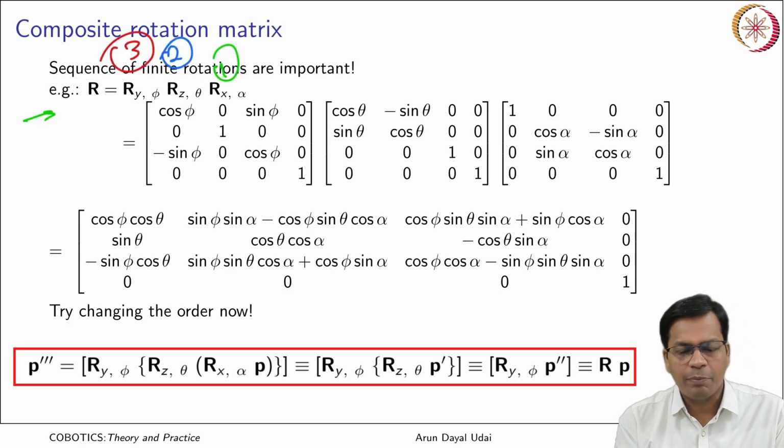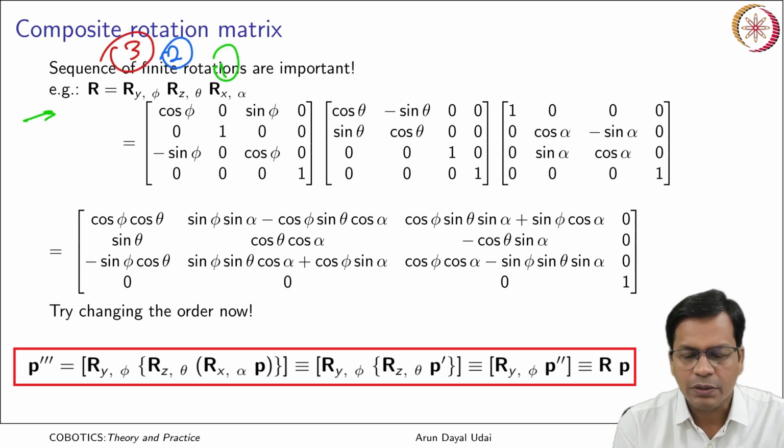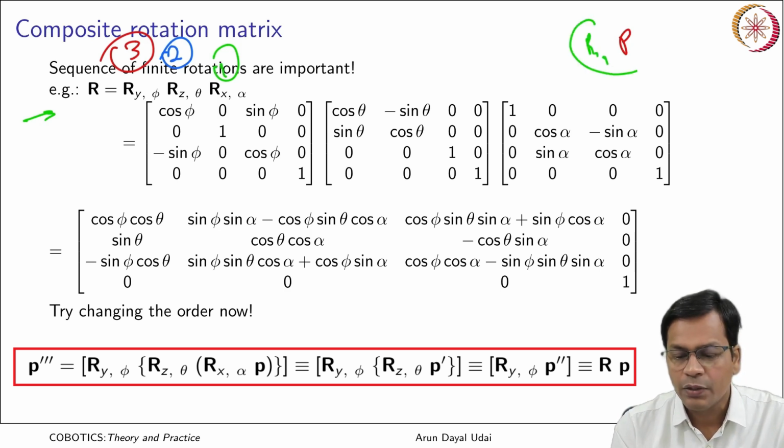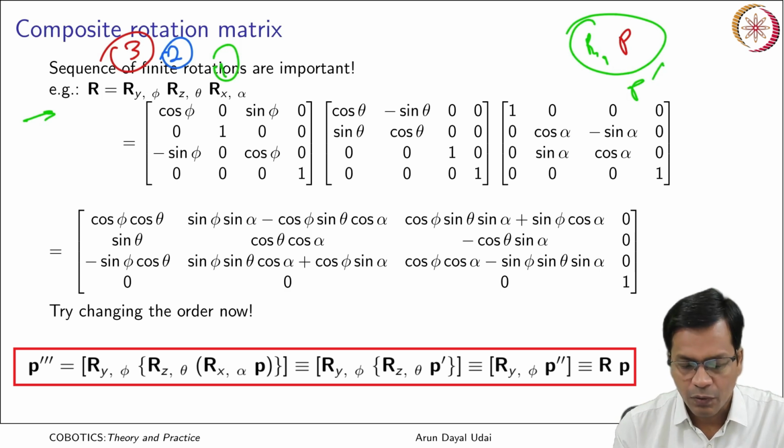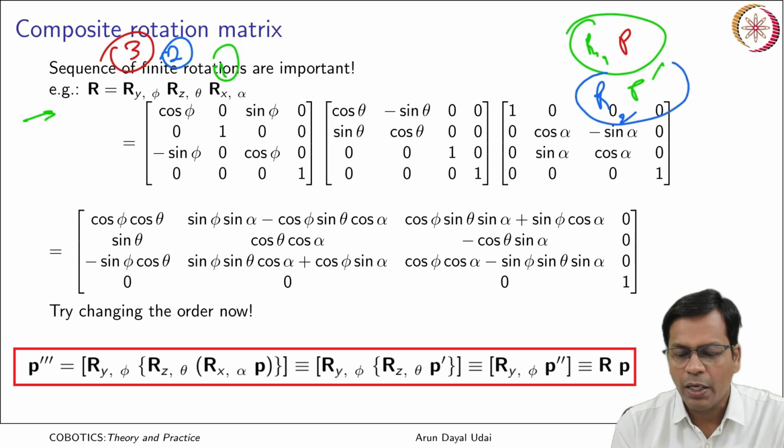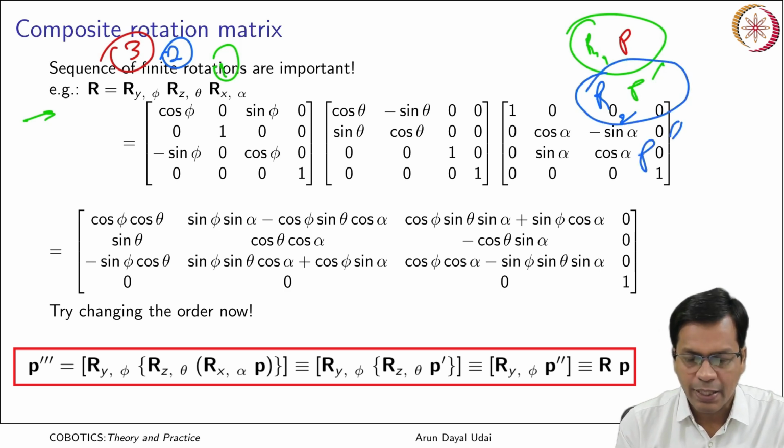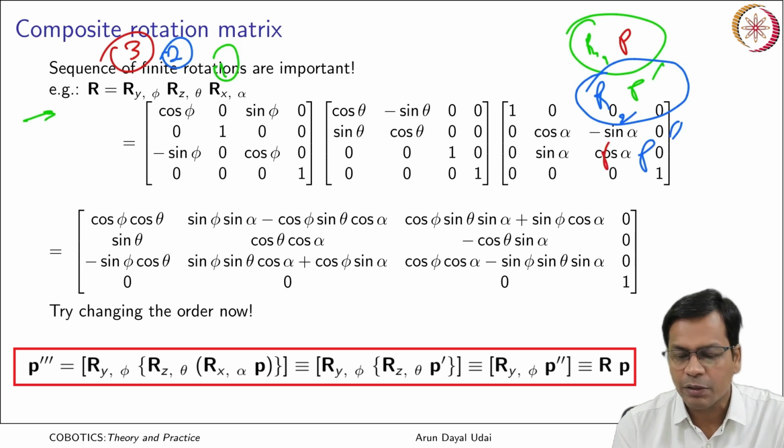They are pre-multiplied. Okay. Because let us say this is the point, you applied a transformation matrix 1 here. This gives you a new point P dash. This is applied with the next rotation matrix, and this gives you a new point P double dash, and again this is applied with a third rotation matrix and this takes you to the final point P triple dash.